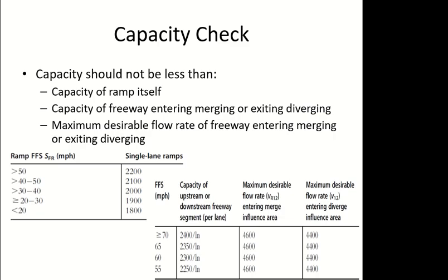For the first two checks, if you violate them, the level of service is F and the analysis stops. The last one, these are not two checks, because either you will have the merge section or the diverge section. You cannot have both in one segment. So if you have a merge segment and you did not satisfy this check, we will continue with the analysis.